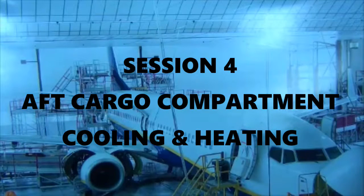So we have the heating. With the heating, we're still dealing with bleed air, but the bleed air is going to actually come from the APU, and it's going to take that bleed air from the APU and mix it with cabin air, and that becomes the ventilation system for the aft cargo compartment. The hot bleed air is going to go through a pressure regulating valve, like I just mentioned, as well as that trim air valve I just talked about. So it's basically going to take all of that air and mix it with the cabin air before it goes into the cargo compartment.